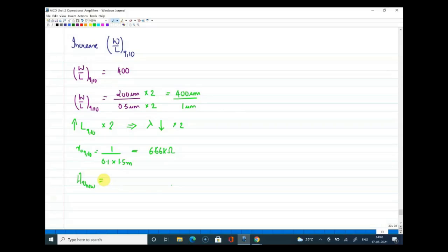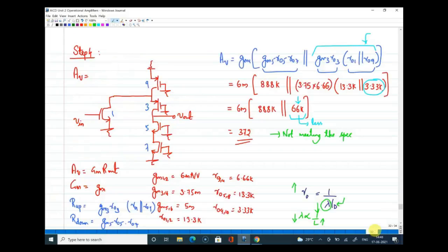So what you need to do is check for this and improve the resistance, and thereby you can bring up the gain value. Your gain value should be somewhat close to 2000. It should not be less than 1000. It should be close to 2000.